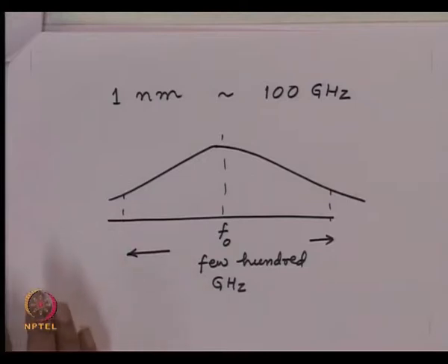So obviously, whatever conclusions we could draw for the distortionless signal from the amplitude modulated system in radio frequencies, those arguments are no more valid, because now the spectrum sidebands are not clearly visible. And if that is the case, then our understanding now has to be completely modified in analyzing the distortion of the signal with optical carriers.